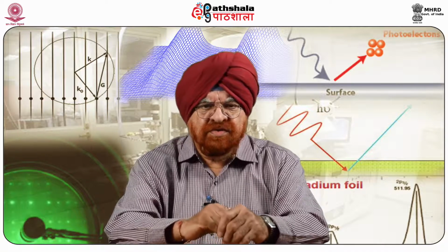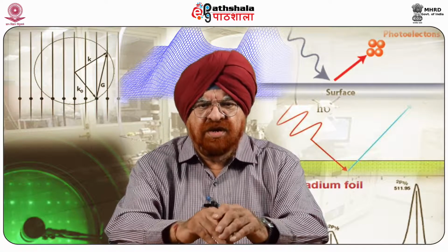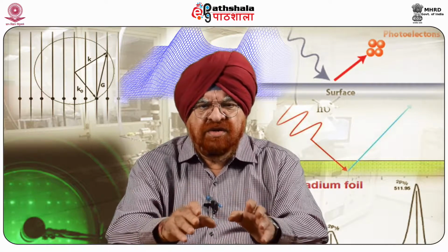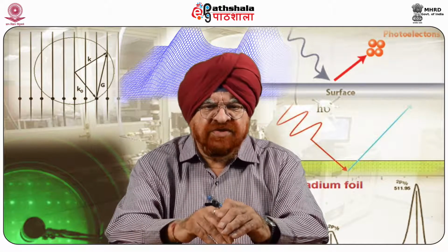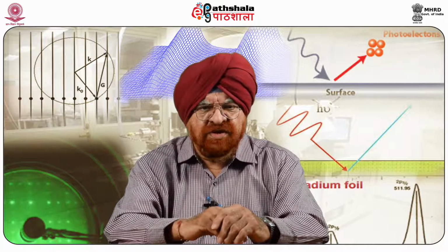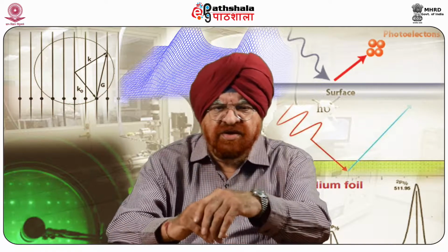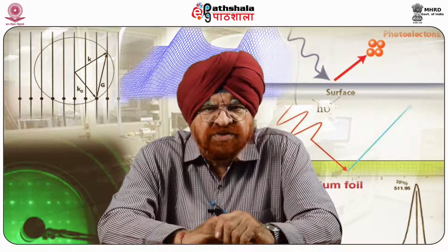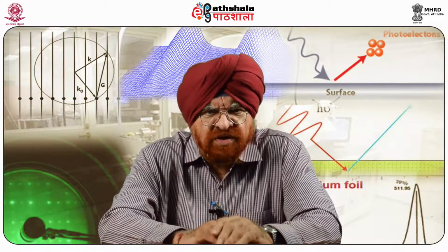This slide deals with the characterization of several technologically relevant semiconductor surface layers by means of two surface sensitive measurements: reflection high energy electron diffraction (RHEED) and low energy electron diffraction (LEED), which visualizes the reciprocal lattice of a surface layer studied under this.